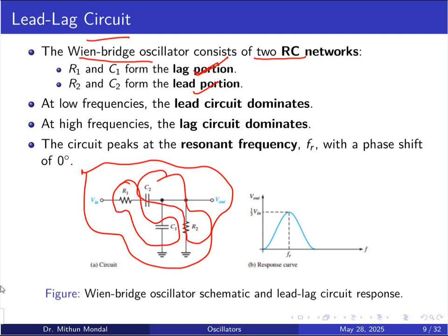So what happens with the frequency response? At low frequency, the lead circuit will be dominating, and at high frequency, the lag circuit will be dominating. The circuit peak will be achieved at the resonant frequency with a phase shift of 0 degrees.